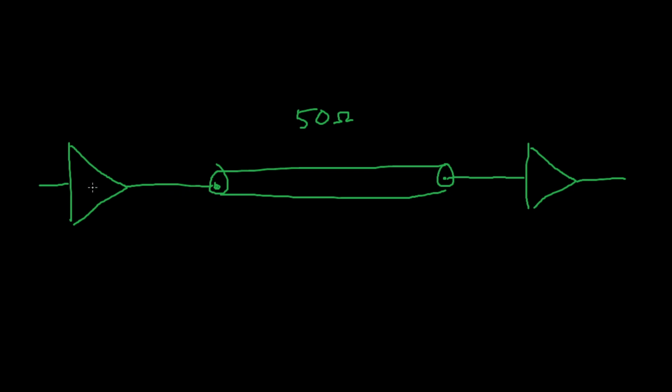So, whenever we turn on our driver over here on the left side, this is what I'm going to be calling the transmitter or the driver, then the receiver we want to pick up our logic signal. This transmitter is going to have an output impedance somewhere around 10, 20, 30 ohms, depending on the type of device. Let's just pick 25 ohms to have a round number. We're going to imagine that this is a very long transmission line, so long that we have time to talk about how things work in it.